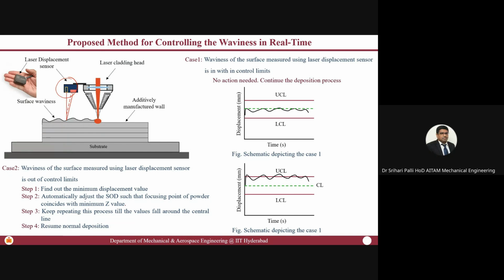Okay. So he is correct. During the stop and the start, there is an additional deposition. That happens because you look at any kinematic system. When you set a velocity of, let us say, 1000 mm per minute, and the moment you press the start button, if you assume it is reaching 1000 mm per minute instantly, then its acceleration is infinity. Now, that is not possible.